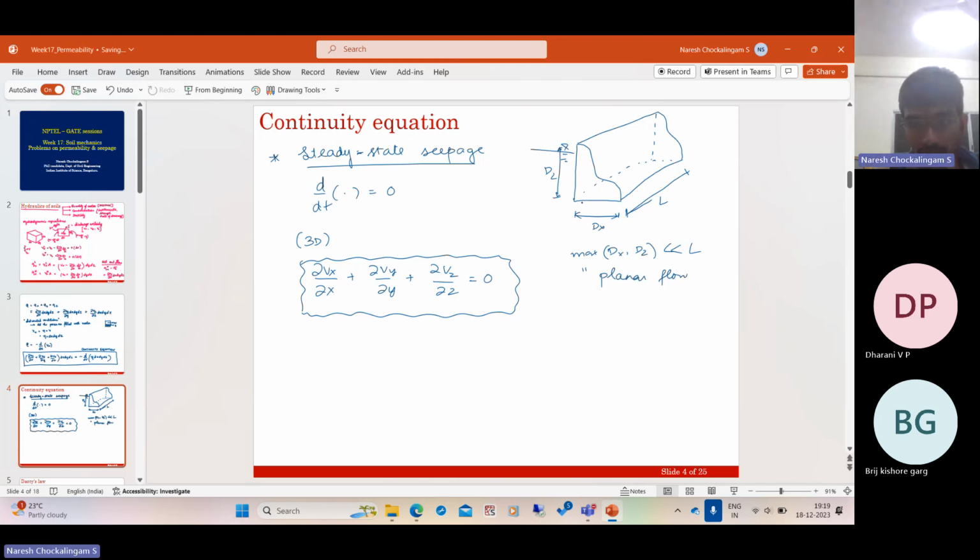That is, the water seeps through the soil. So there is soil here. Water seeps through the soil below the dam to the other side because soil is permeable. It's not like a rubber sheet, so it is permeable. Therefore, water seeps through this. But since the dam is so long and the water level is almost the same throughout, there are no changes in elevation or anything.